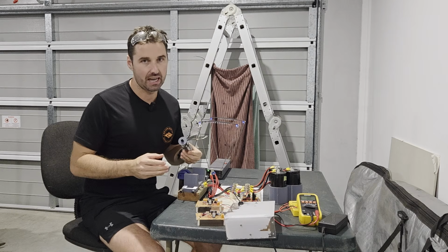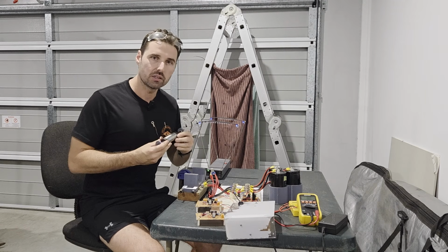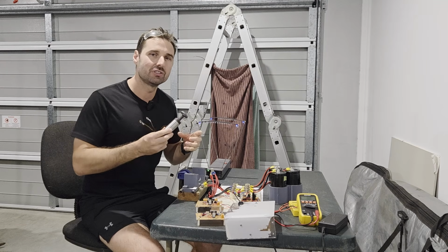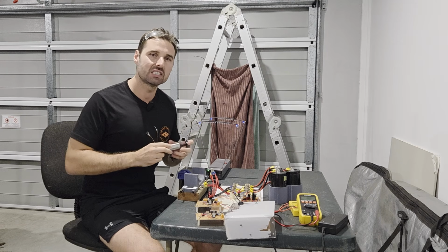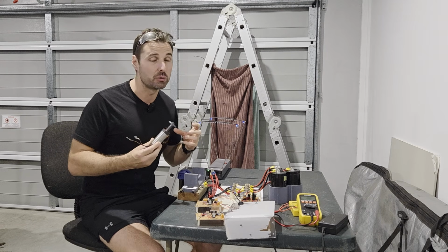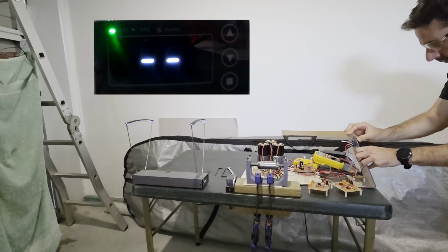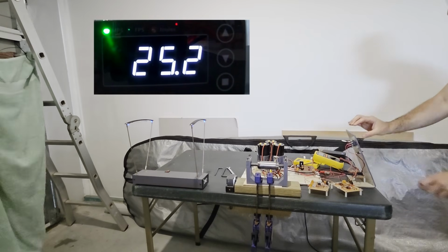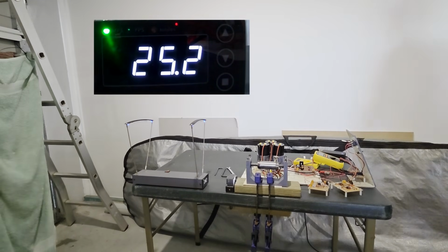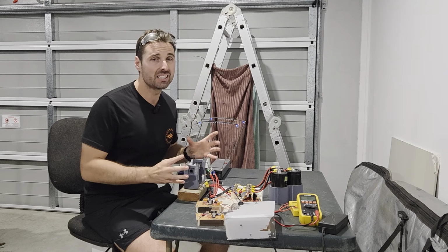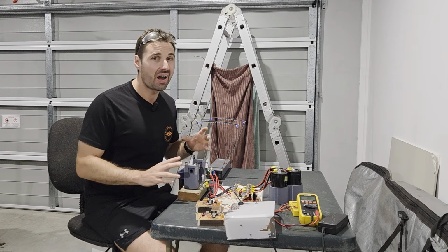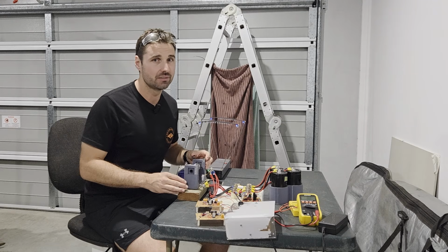So what are we expecting to happen? Will the lower reluctance of the magnetic circuit make a difference? Or will the slower current ramp due to the increase in inductance mean there's less current overall contributing to building the magnetic field? When testing the coil with the external shell, we measured a slightly lower velocity than the baseline at 25.2 meters a second, which appears the reluctance of the magnetic circuit wasn't decreased like we thought it would, or there are other unknown factors at play.